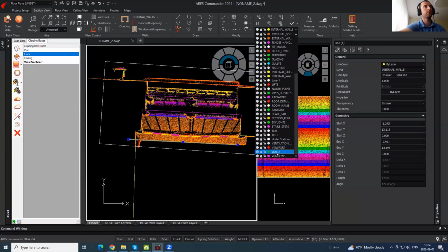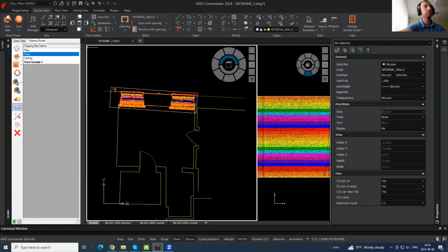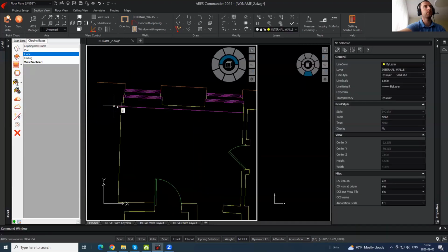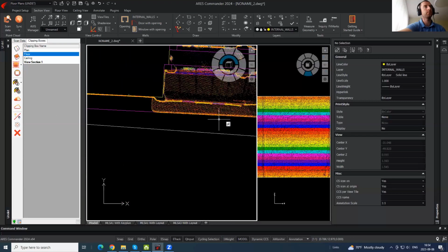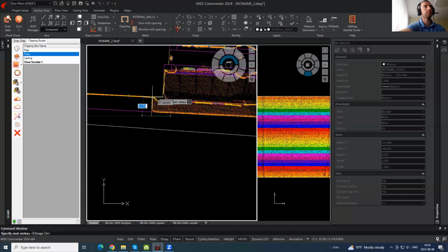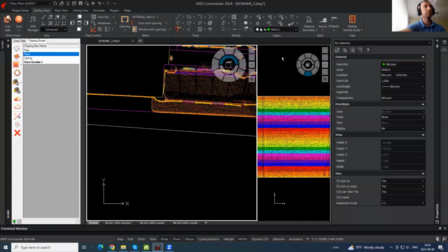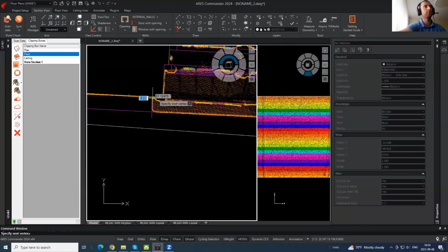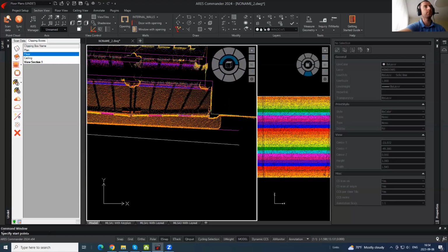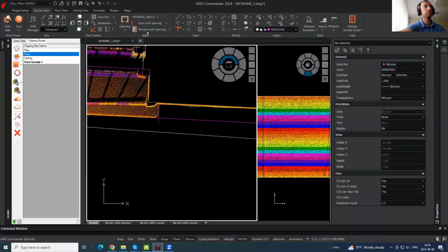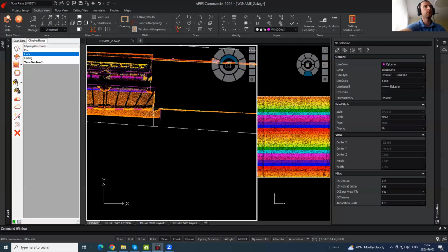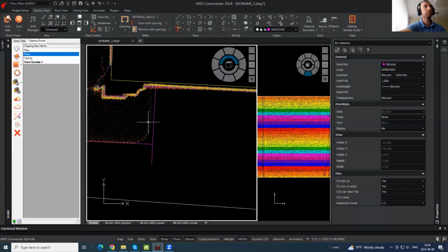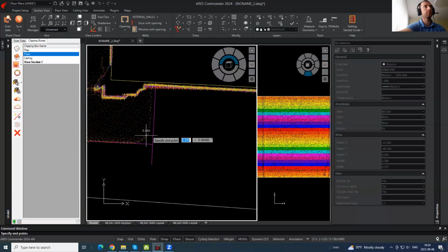Let's move to Windows layer. I can switch off, extend that line, see if it fits. It's all right, it fits. Just draw the ends. Okay, switch the layer, the windows. End lines, one line, another line. Trim what is between. I can use fillet command because it's a little bit curved.